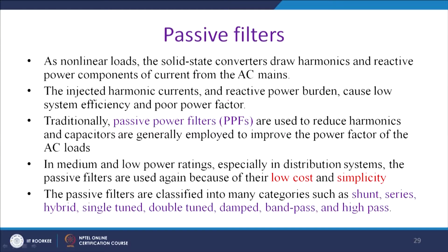The nonlinear loads, the solid state converters, draw harmonic and reactive power components of current from the AC mains. The injected harmonic current and reactive power burden cause low system efficiency and poor power factor. Traditionally, passive power filters, that is PPFs, are used to reduce harmonics, and capacitors are generally employed to improve the power factor of the AC loads, at medium and low power ratings, especially in distribution systems.